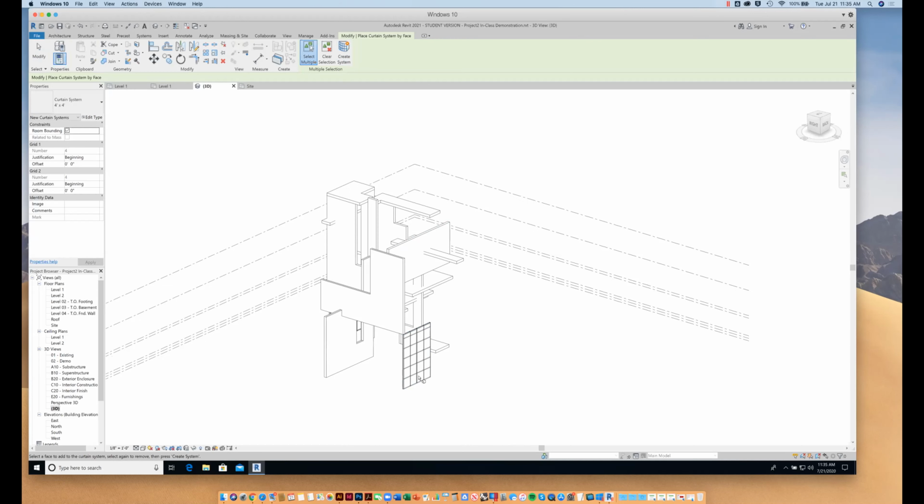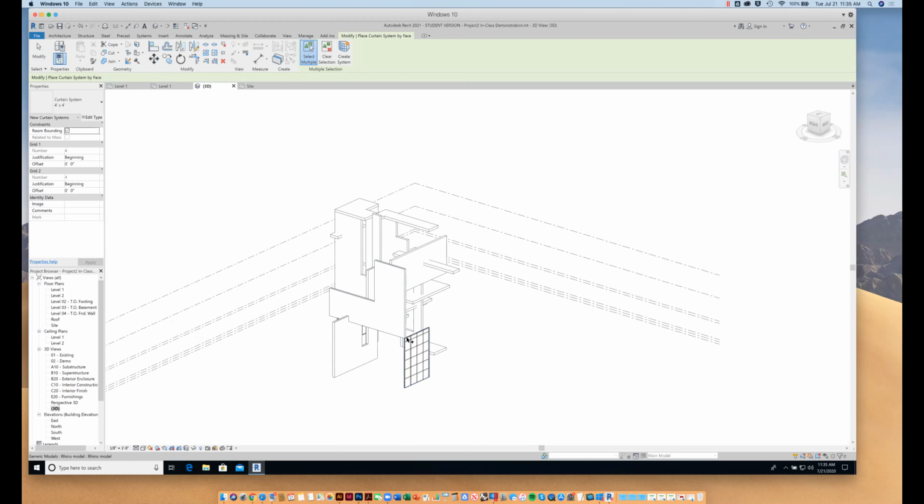Now, what's interesting is that the height of this isn't necessarily based on a 4 foot module, right? First of all, I was picking 24-inch modules, 2 foot modules, or 48-inch modules, 4 foot modules, for a reason. If you think about all standard building material construction sizes, we have masonry, which is usually based off of the 2-inch, 4-inch, 8-inch, 16-inch modules. We have plywood and wood framing that are based off of a 16-inch module, like 16 inches on center for studs, 4x8 sheets of plywood, and drywall and those sorts of things.